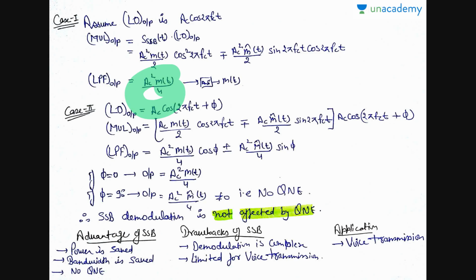as it only allows the lower frequencies but rejects the other frequencies, and we can recover our message signal back from this, as the amplifier amplifies it, and in the amplifier the blocking capacitor blocks the DC component, and we will get the message signal in the output.